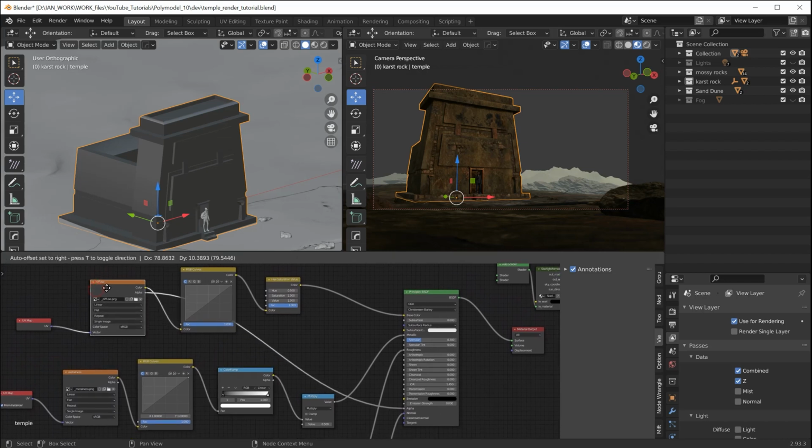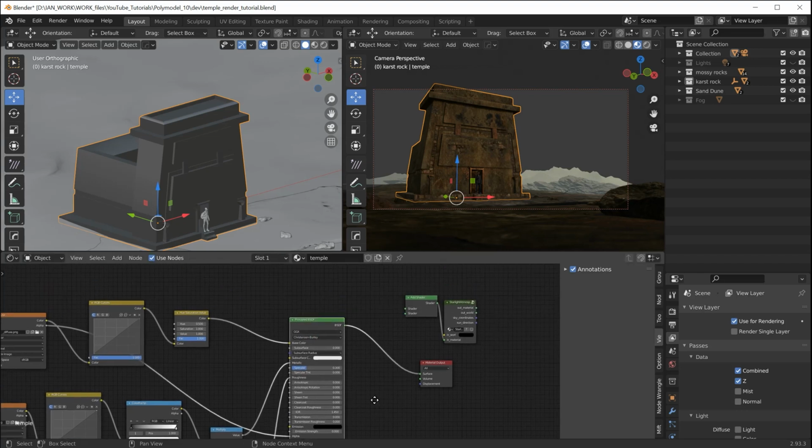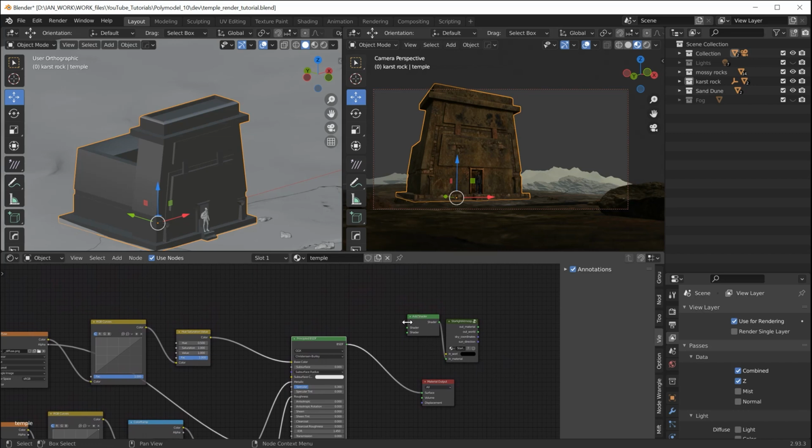You'll notice here that when we exported from 3D-Coat, we also exported in our diffuse, we exported an alpha channel as well. And if you've got alpha information, which we don't have actually on here, then that alpha can be plugged into the alpha channel of our shader here as well. Okay, so once that's done, we rinse and repeat for all these objects here. Sometimes when you bring in FBX, it'll automatically connect those up anyway, and you won't have to do any of this, so it makes life a little bit easier for you.